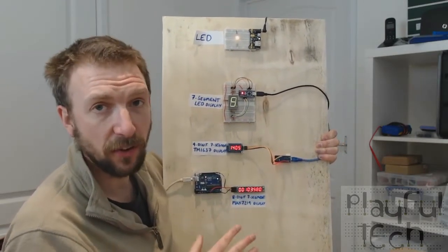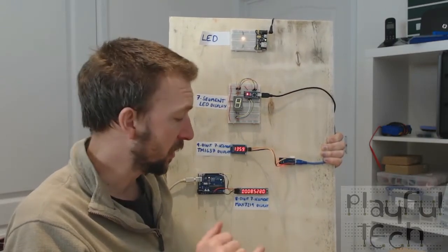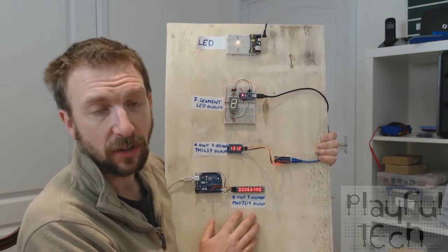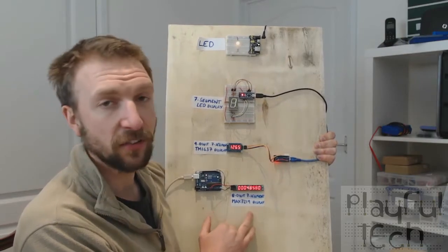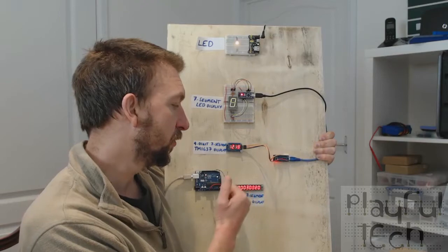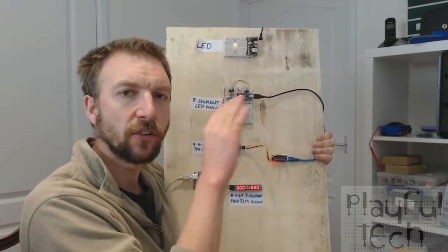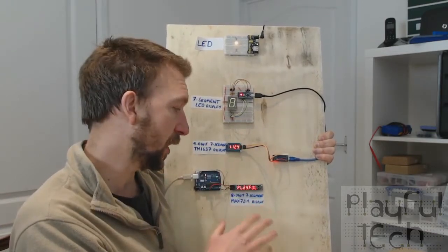And as I said, there's several different controller chips, and each controller chip comes with a different library as well. So here, for the 8-digit 7-segment display, this has got a different sort of controller on it. This is called the MAX7219, and that controls 8 digits like this in a line, and the controller can also be used to control an 8x8 grid of LEDs as well, the same controller.